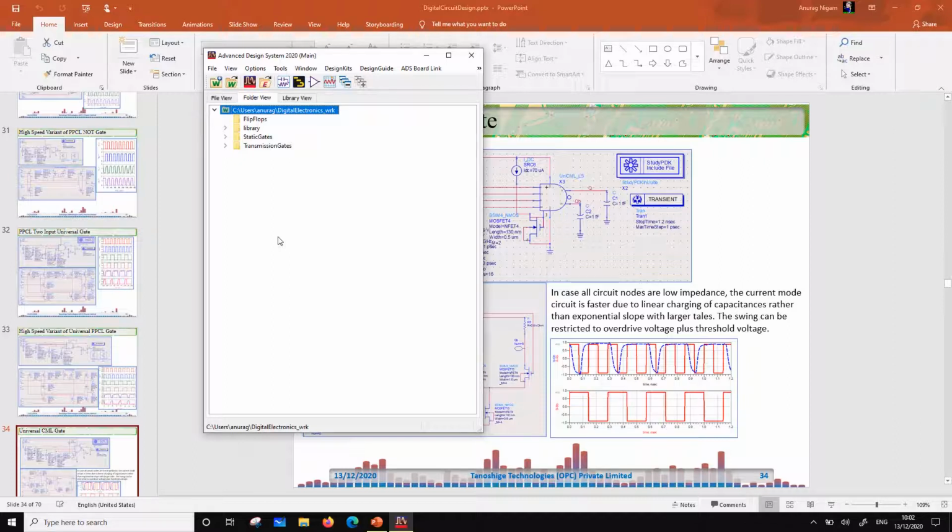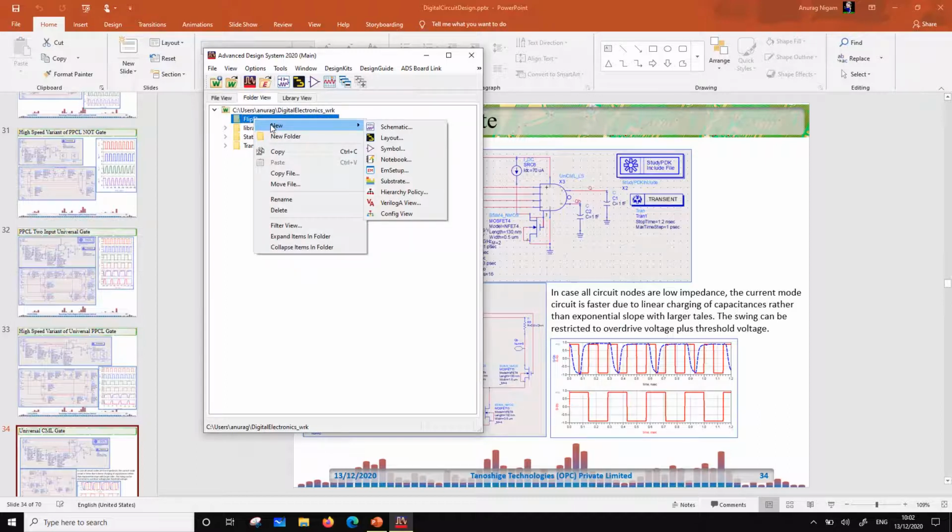Now there are two ways to do it. One is you can use a master slave. So basically a master responds to one of the edges and the slave responds to the other edge. So this is a master slave configuration. The other one is you can just design based on delays and a feedback loop. You can design a flip-flop. Okay, so let's start with a very simple implementation.